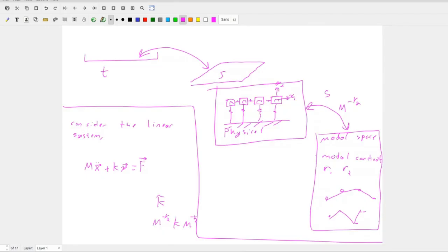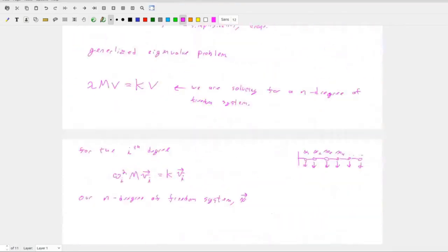And there are things like laser vibrometers. You can take a laser and shoot it at a panel and move the laser around. You can get the displacement at a very fine resolution over an entire structure. It just takes hours. So again, we live in a physical space. We want to come to a modal space, grab our frequencies of interest, and pull them back out. Does that make sense, from a conceptual standpoint? So this is x of t, and it's a vector, one for each of the degrees of freedom that we're considering.